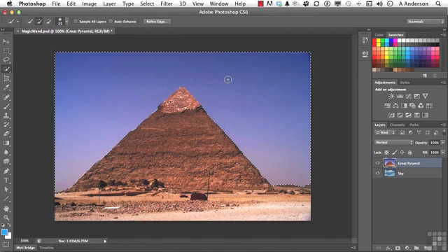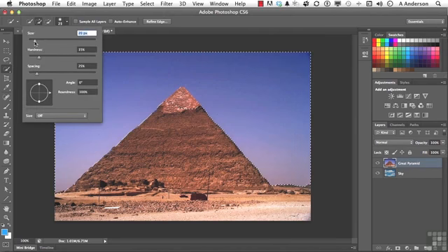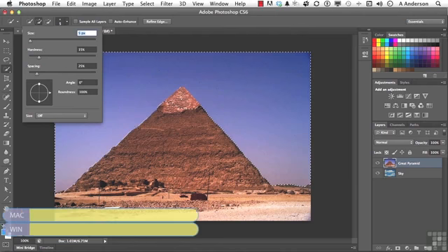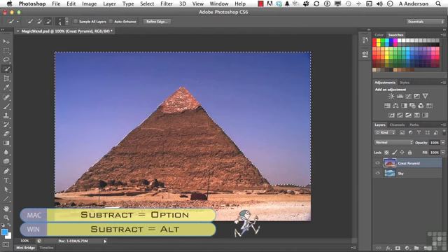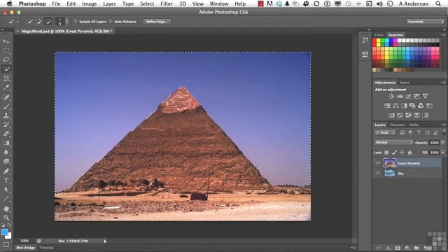But you say, well, you got the cap here, part of the selection. And down here, there's just a little spot right there that looks like it needs to be kind of taken off the selection. Let's start by reducing the size of our brush. Let's make that a little smaller. And then come back over here. Now, if you hold the Alt key down with this tool, it will begin unselecting areas that were part of the selection. And we very carefully paint back over like that. Down here, the same thing, a very small spot. But we hold the Alt key down and we just kind of wipe into that area.